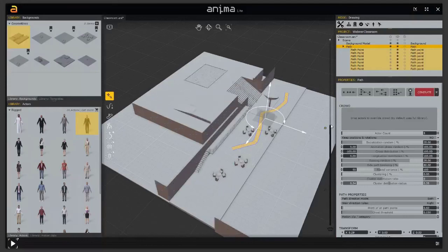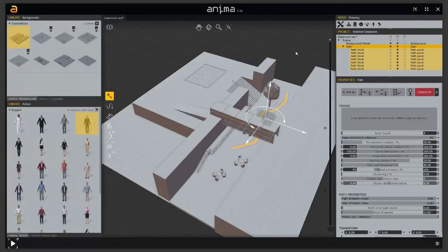And then what I usually do is just to create a bookmark for the whole model without sections, okay? So here, add point at current height. Now, last thing I want to show you is this. If we hover these little dots, a little tooltip appears, a little label. By default, it tells me the height of that section plane. But what we can do, for example, is to rename it.